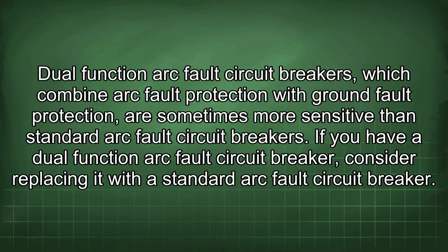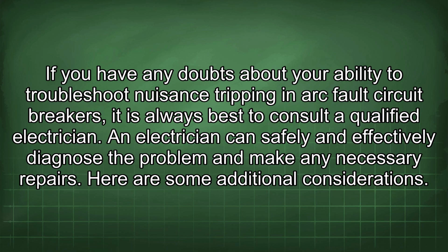Dual-function arc fault circuit breakers, which combine arc fault protection with ground fault protection, are sometimes more sensitive than standard arc fault circuit breakers. If you have a dual-function arc fault circuit breaker, consider replacing it with a standard arc fault circuit breaker. If you have any doubts about your ability to troubleshoot nuisance tripping in arc fault circuit breakers, it is always best to consult a qualified electrician. An electrician can safely and effectively diagnose the problem and make any necessary repairs.